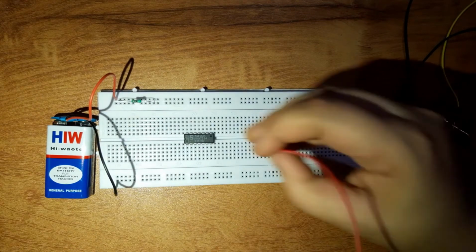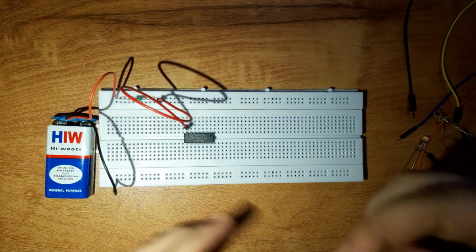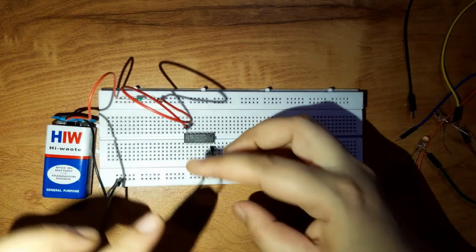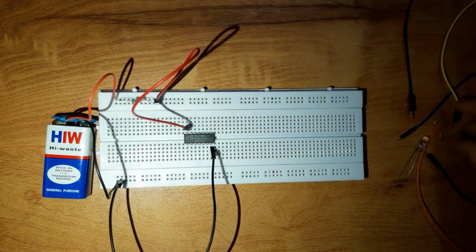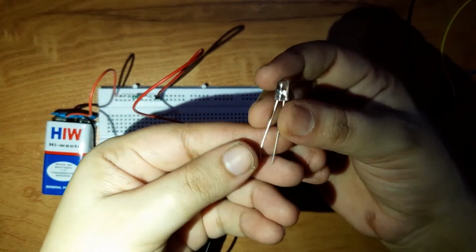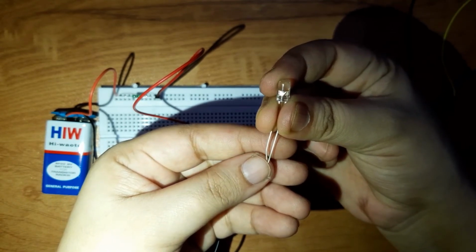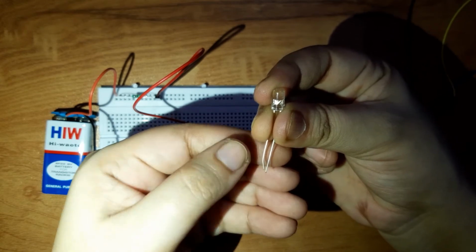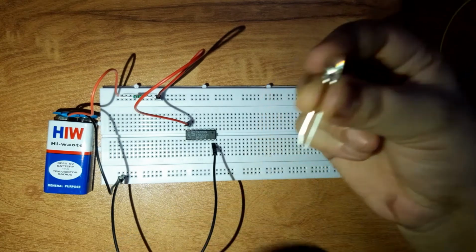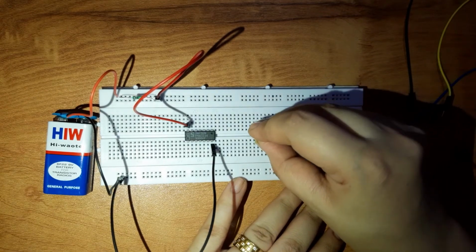First of all I will be connecting the 14th pin of the IC to the positive side and the 7th pin of the IC to the ground. Now the output can be seen at the LED. To identify the LED's positive and negative side, the leg which is longer is the positive and the leg which is shorter is the negative. Also you can check that the small filament is the positive and the broader filament is the negative. So you can place this LED somewhere here like this.